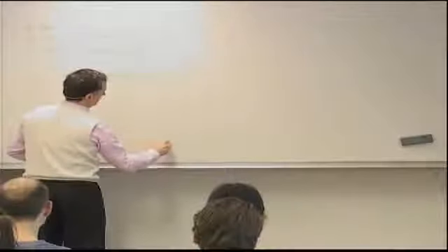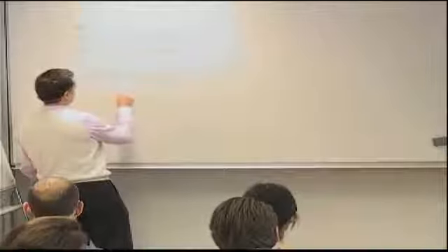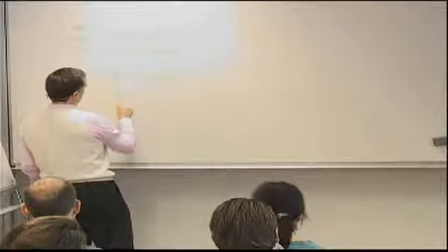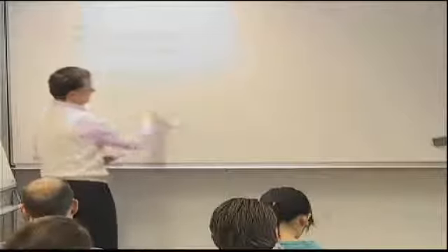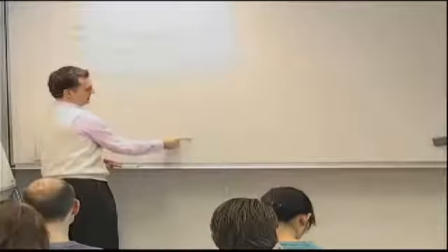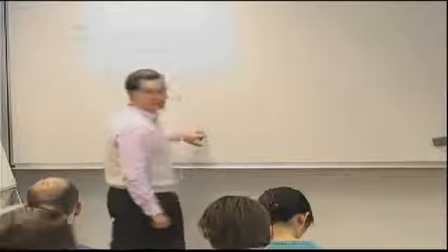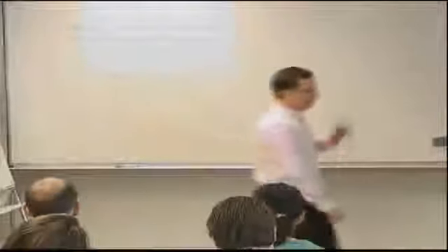And if you remember from our plots for crippling versus B over T, we start with a nearly horizontal line, and then it goes down, this being the crippling stress divided by the ultimate compressive stress. So this reduction means as I increase B, this is going down, which is not good. At the same time, as I increase B, my moment of inertia is going up, which is really good.